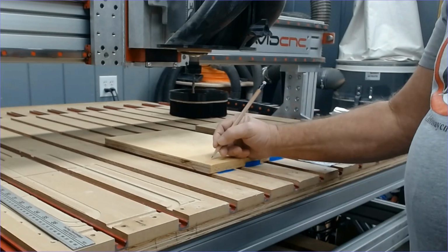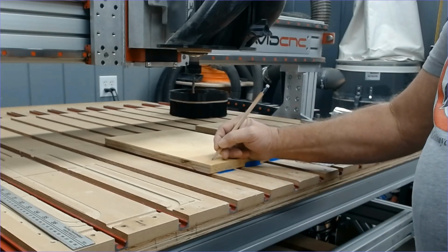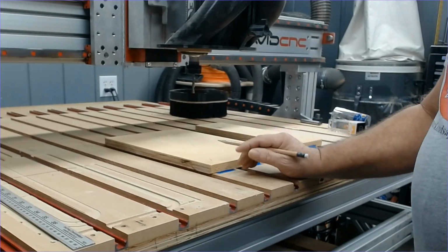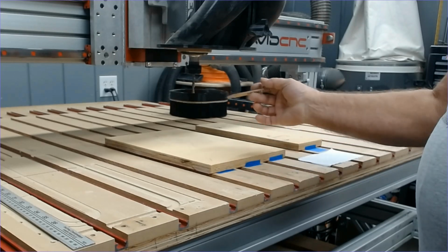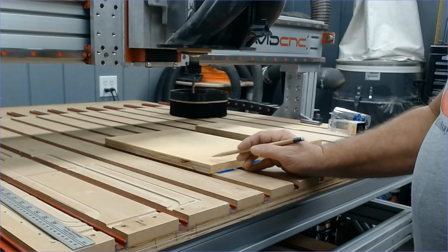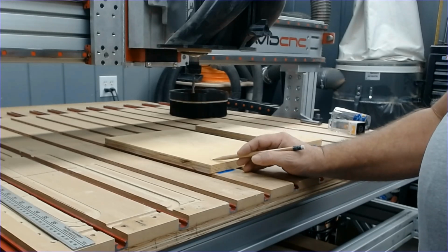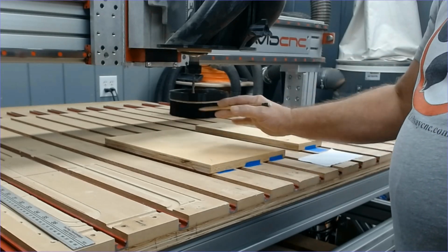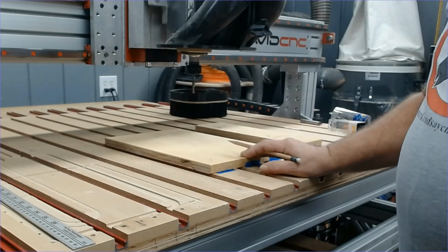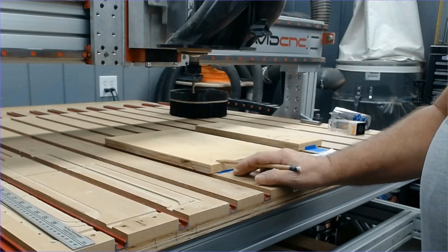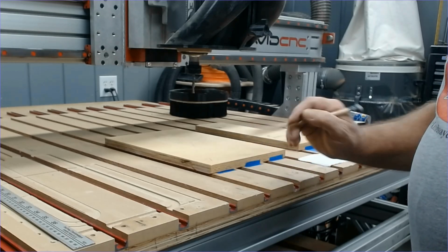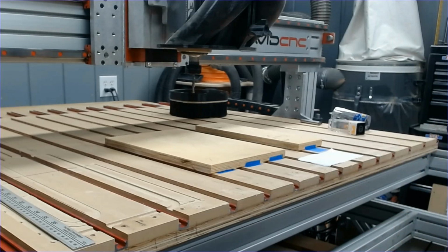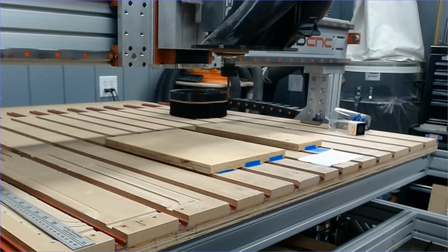Pick a spot, and it doesn't matter where. Just pick a spot that's not going to be machined away and draw a little X or make a little circle. Mark it in some way. Then every time you set your Z0, set it at that point. That way, if there's any distortion out here, or you end up removing the spot or carving into the spot where you set your Z0, you have a Z0 position out here somewhere that's not going to be affected by that carve. So, let me go ahead and bring my axes over here.